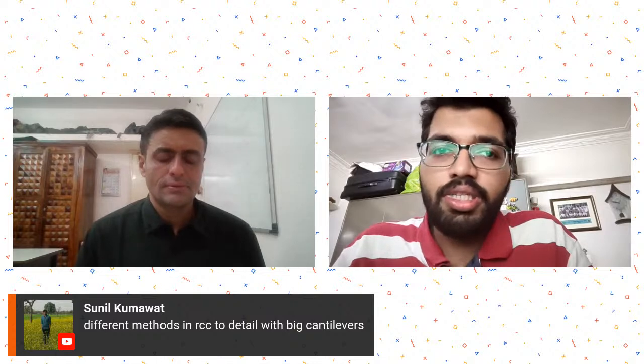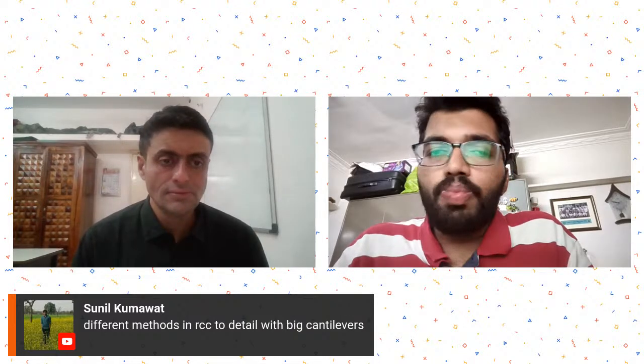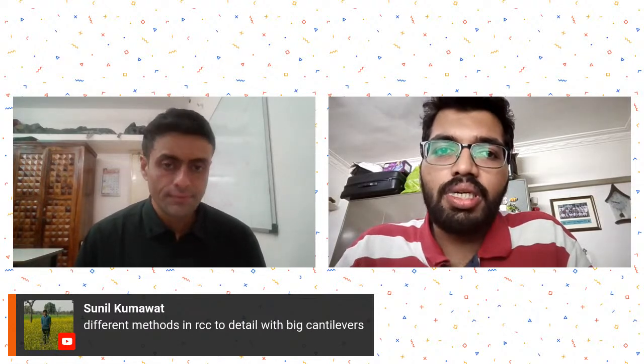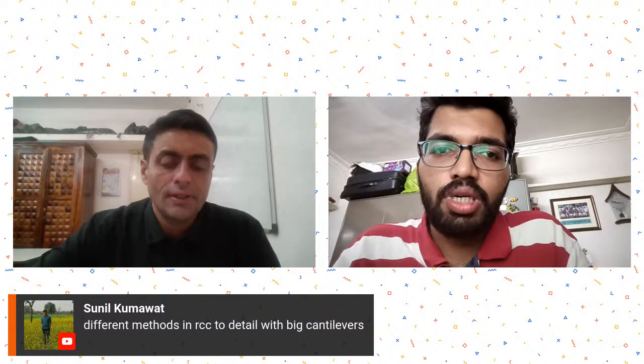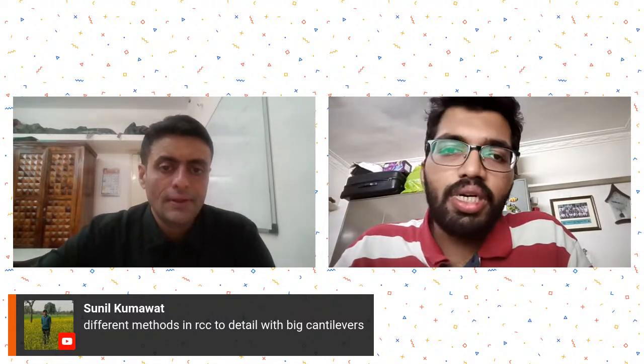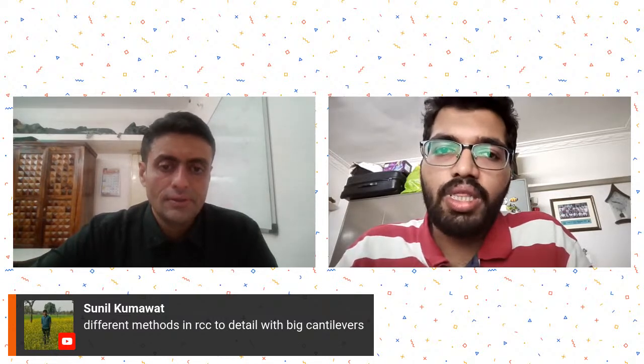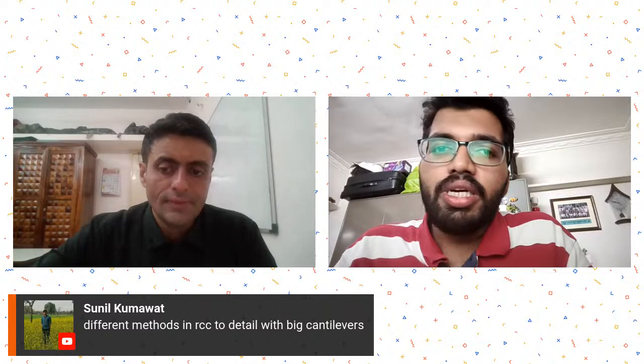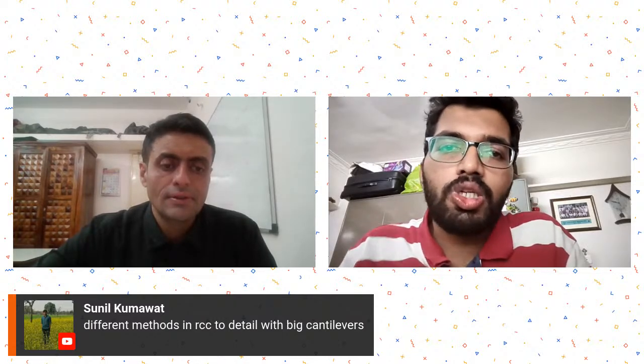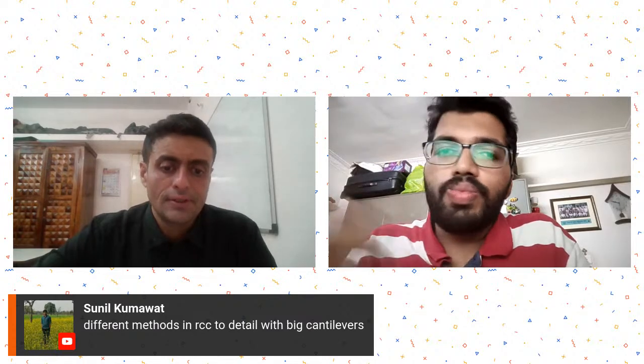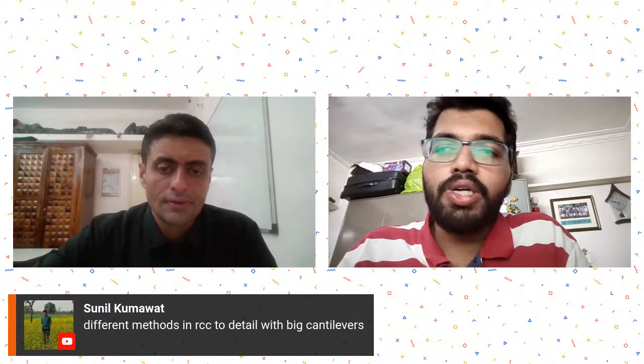Yes, so we were basically checking the tip deflections to be within the permissible limit of L/250 as per the code. Also, there were high shear failures in these girders, but we are planning to provide a structural steel plate inside to increase the shear capacity of the girder beams. Using the steel shear strength formula, the thickness of the plate will be determined accordingly, and shear studs will be provided based on the horizontal shear stress diagram. That's how we will increase the shear capacity.